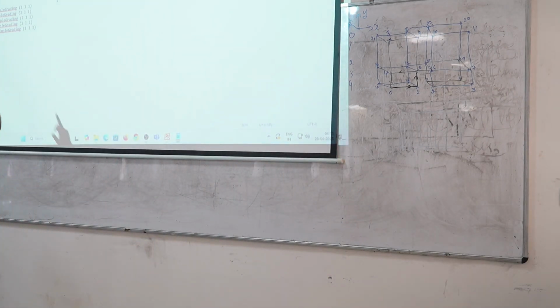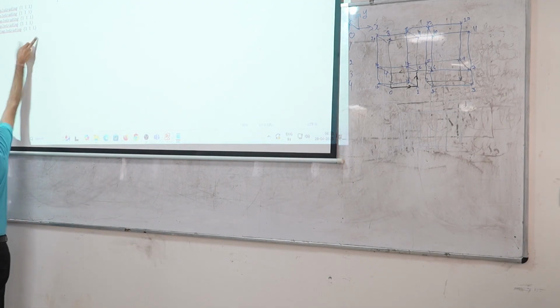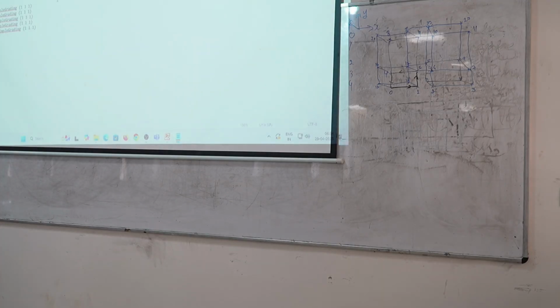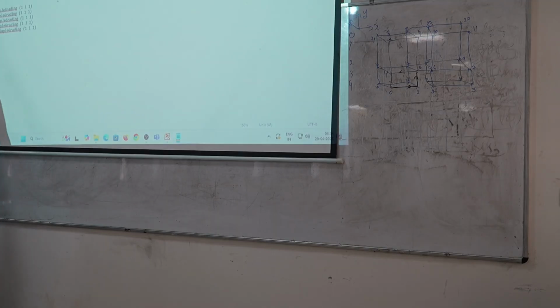When in simple grading I write 1 1 1 everywhere, it means it will place the cells uniformly. But if in the x direction I write 0.1, and it is doing 19 divisions in the x direction, the left face will be made 1/10th the size of the largest cell present on the other side, and accordingly it will gradually adjust the cells.